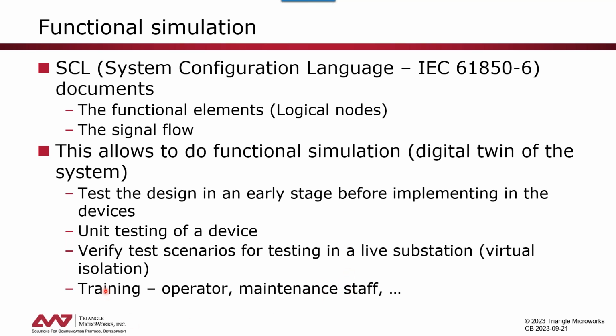So we can also use the simulated environment for trainings. Operator training, maybe another thing. When you want to train an operator on your SCADA system, you can simulate the complete behavior using functional simulation, and the operator can be trained on the SCADA system. So that's some of the use cases for the functional simulation.